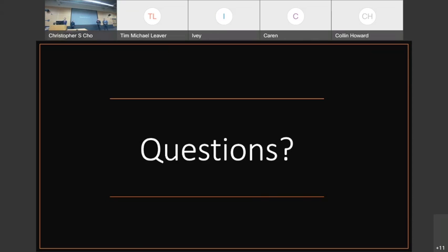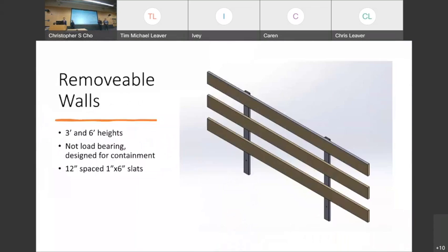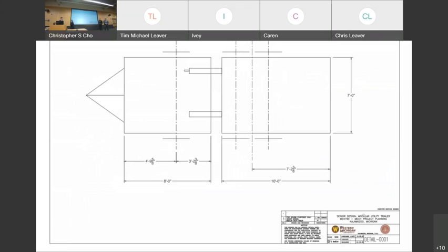Why 17 feet? Park trailers are typically 18 feet, so why 17? So we chose 17 feet based off of the size of the Suburban, of course, but there's also the easier method of locating our axles within the weight distribution study. With 18 feet, we're going to start having a different distribution on those axle locations. Basically 17 feet I found to be ideal. What is 18 feet? 7 feet wide. 8, yes.